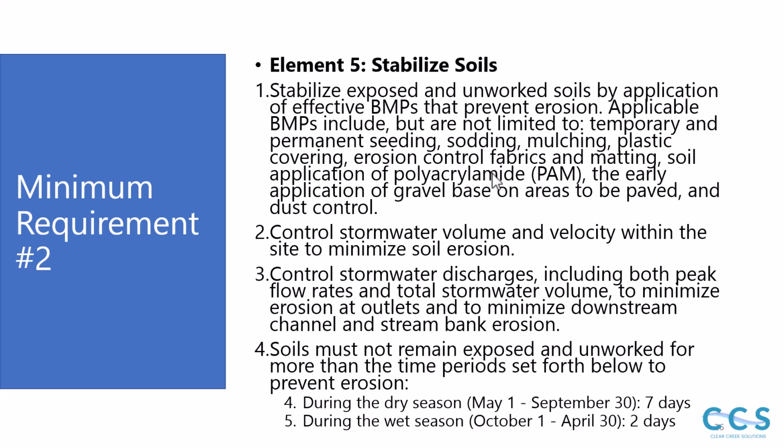Then there's element 5, which is stabilized soils. So stabilize exposed and unworked soils by application of effective BMPs that prevent erosion. Applicable BMPs include, but are not limited to, temporary and permanent seeding, sodding, mulching, plastic covering, and so on. The early application of gravel base on areas to be paved, and dust control. Control stormwater volume and velocity within the site to minimize soil erosion. Control stormwater discharges, both peak flow rates and total stormwater volume, to minimize erosion.